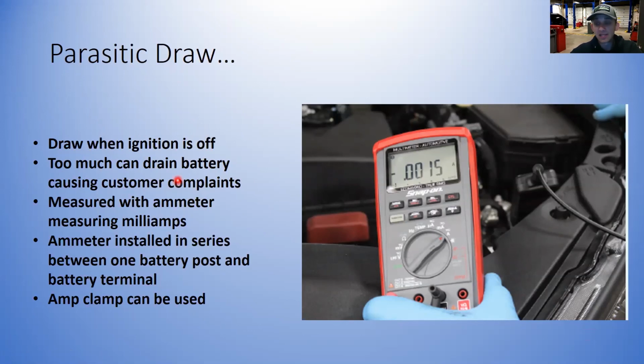So nowadays, a lot of times, even under normal circumstances, if you leave a car sit for a few weeks, it may have enough of a drain that's acceptable that may create a slow start or a slow crank condition. We had customers in the past when I was in industry who came in and said, my battery was slow crank, or it had to be jump started. And I said, well, how long did you drive? Well, it hasn't been sitting that long. I said, well, where was it? Well, we were in Florida for a month and it sat at the airport for a month.